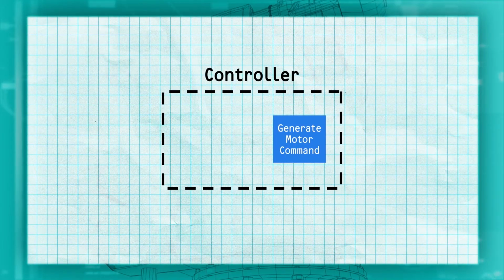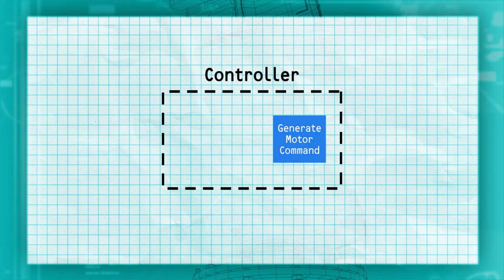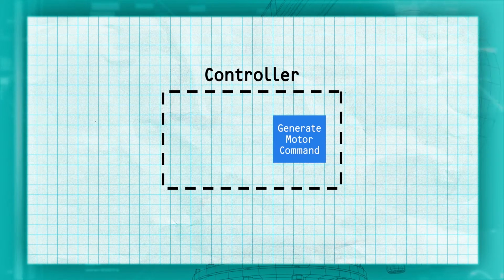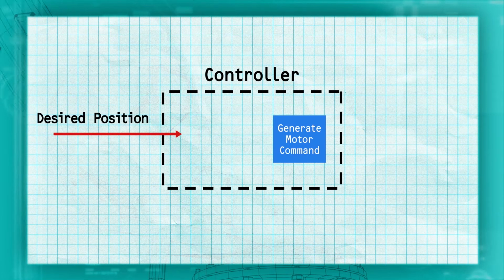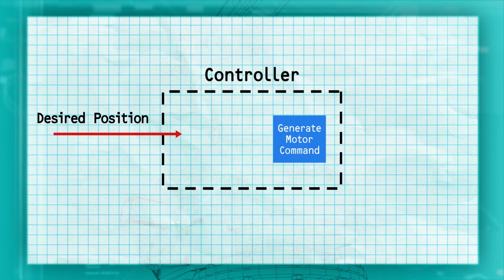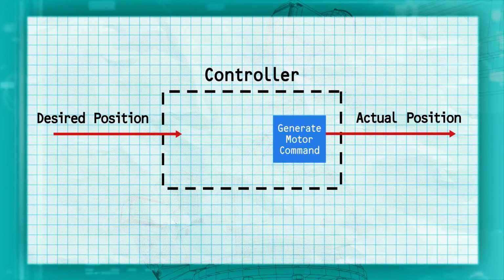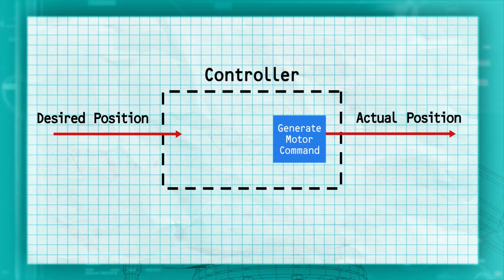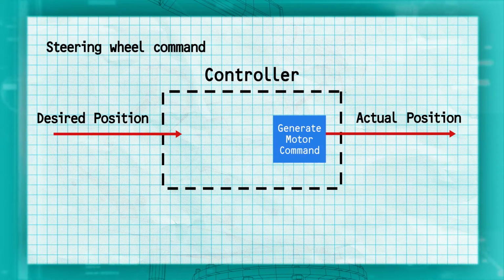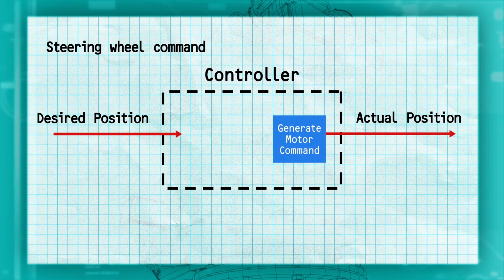The robot has its desired input signal. That's the trajectory the robot is trying to follow. And it has the specific position along that trajectory where the robot is supposed to be. The robot also has its actual position where the robot really is. The controller uses these two positions to determine which direction to go and how much to turn the wheels.